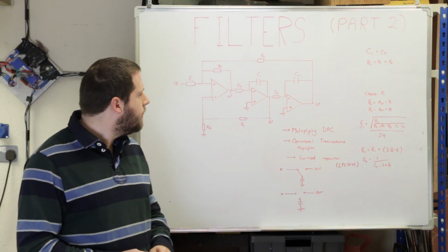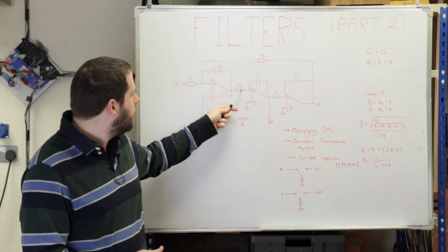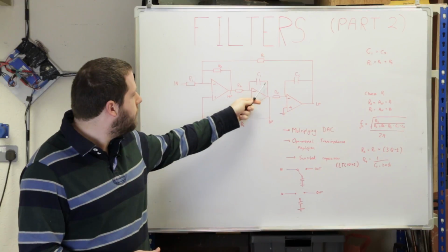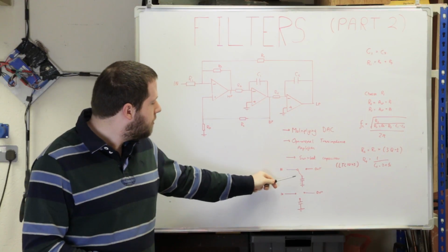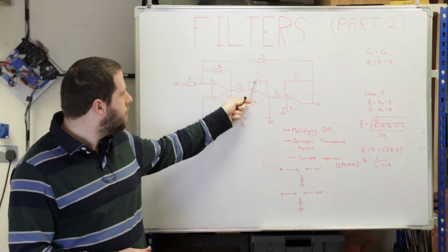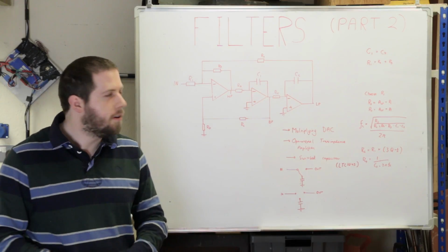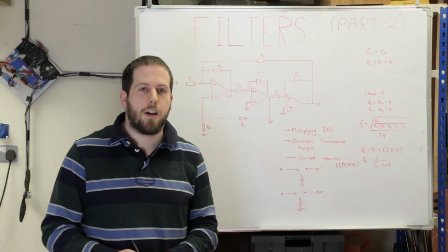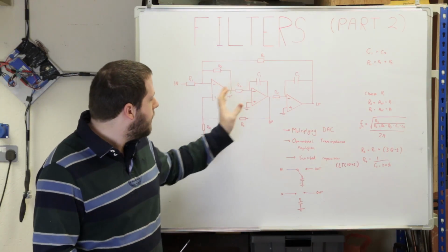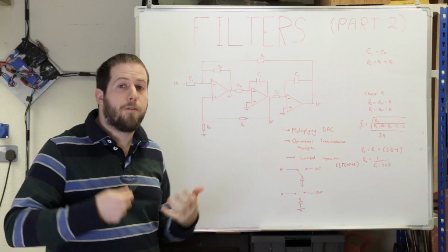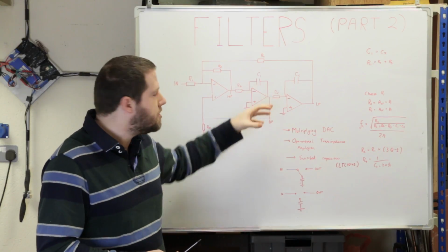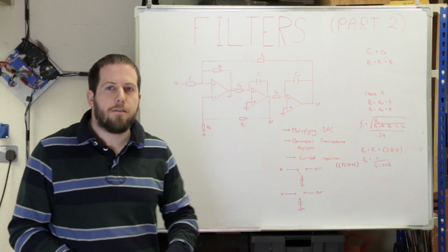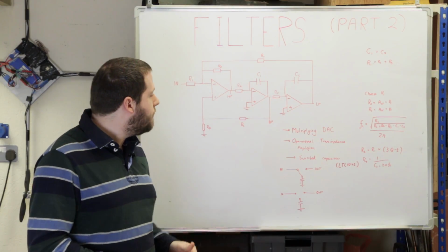Especially in a circuit like this, where you replace R4, say, with a switch capacitor, and you've got an integrating capacitor up here, as long as you make this capacitor quite a bit smaller than C1 and quite a bit smaller than C2, you can turn that switch across, and depending on the speed at which you change that switch, or the amount of charge you're putting through, and therefore the faster you do the switch, the more charge is getting through per unit of time, it's effectively like having a lower value resistor there. So it's quite an effective technique.